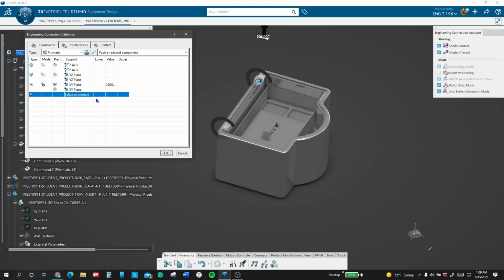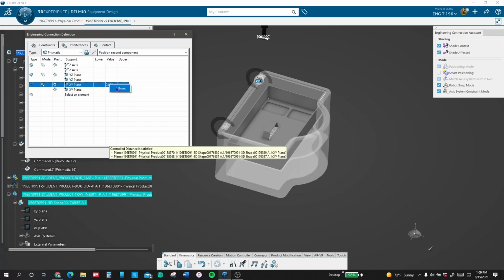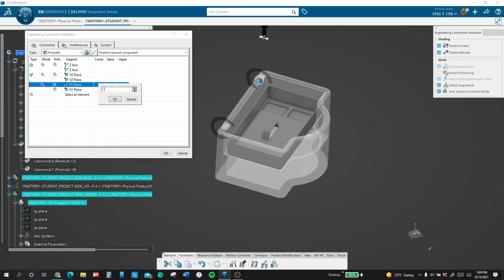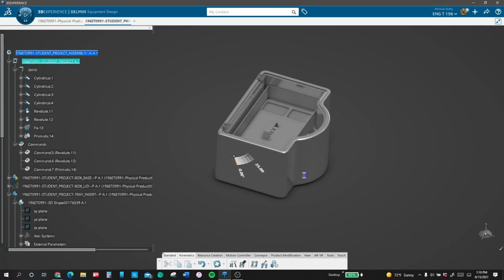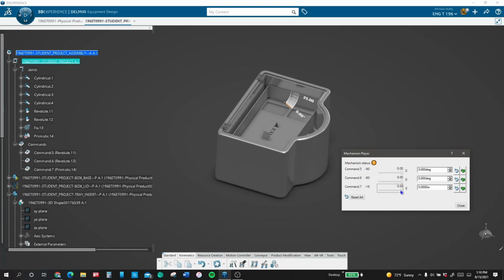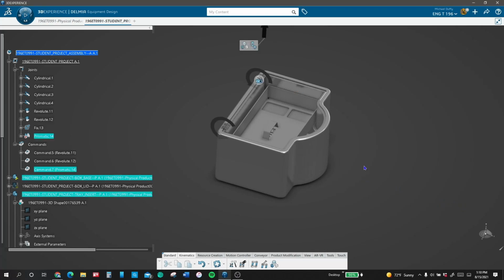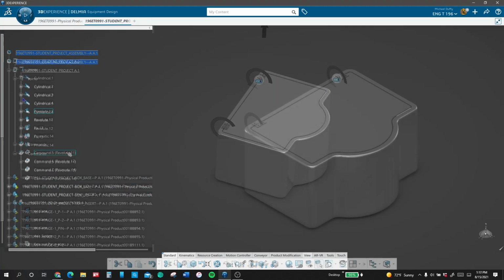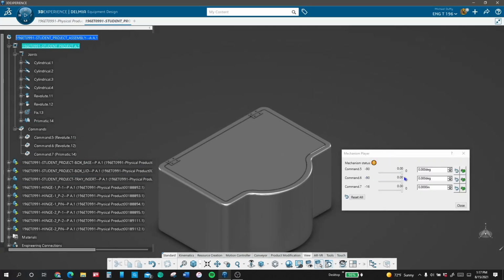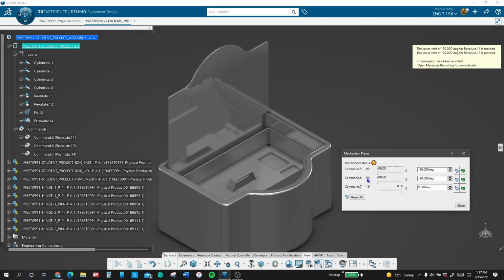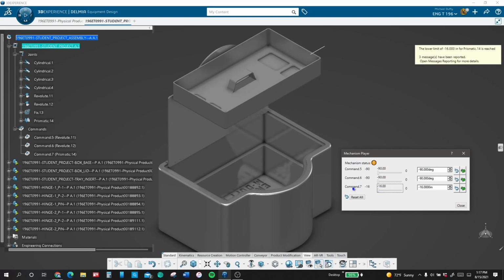So what I want to do is go into the joint itself and adjust the parameters. I unset that center dimension and I set my limits high and low. Grab hold. Now it's doing what we want it to. Alright, now we add a motor to it by going into the simulation workbench. Oh, I'm testing here to make sure it all works.